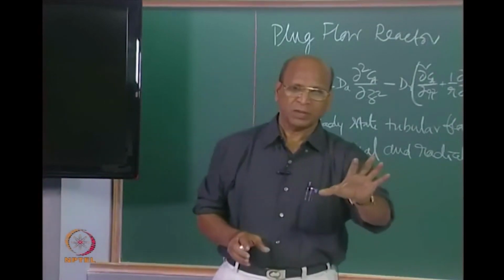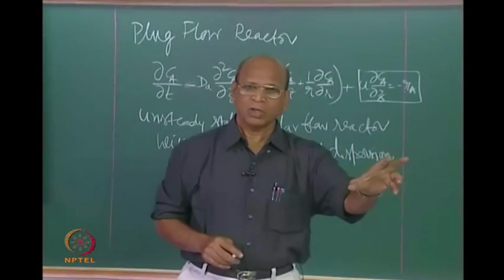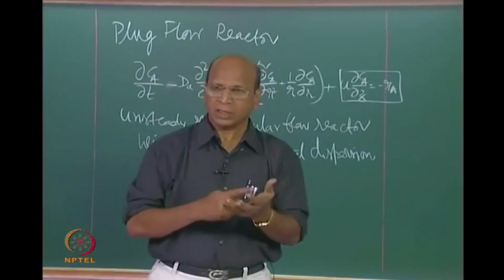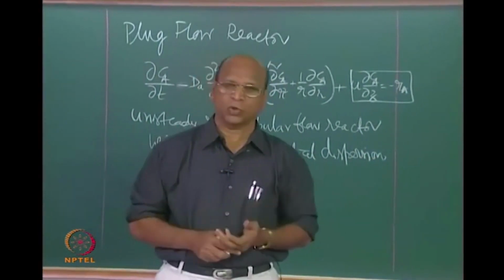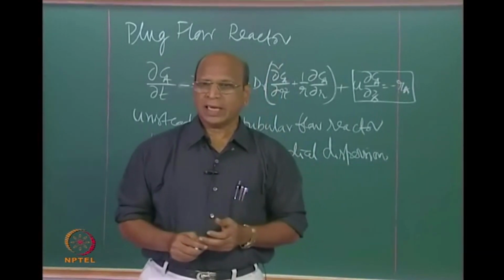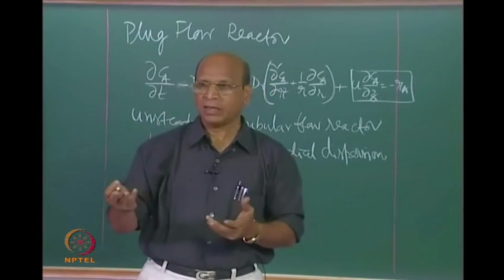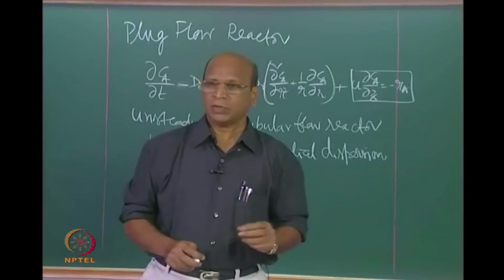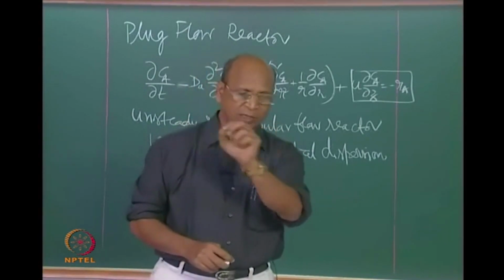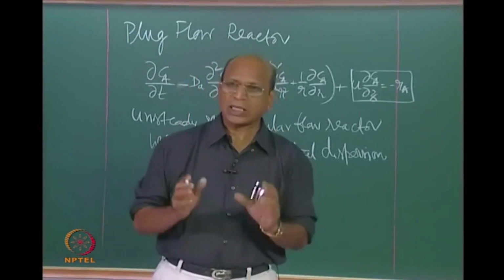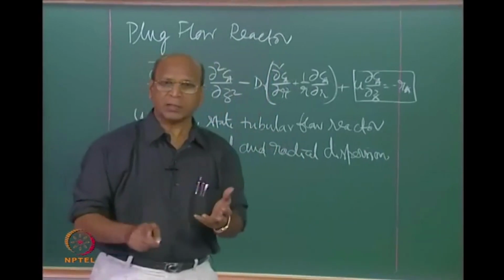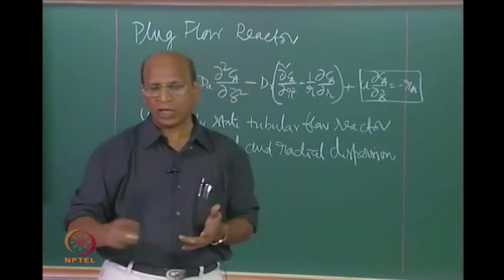That is one way. Whatever is necessary for plug flow, we said that by assumption there is no axial mixing, the radial mixing equal to infinity and flat velocity profile, these two are also enough. And of course all the time taken by each and every particle is the same. All those assumptions tell me that you don't have axial mixing, you have infinite radial mixing.